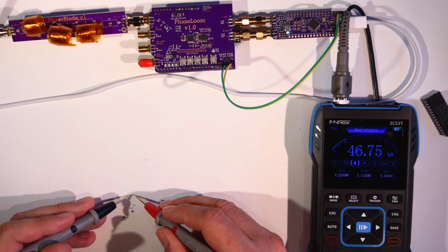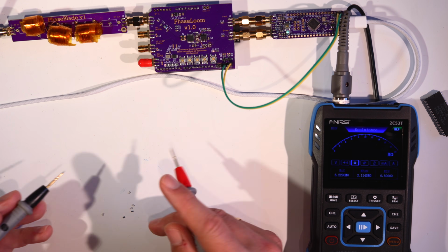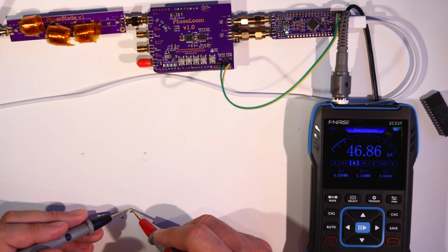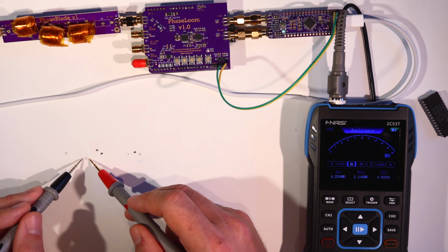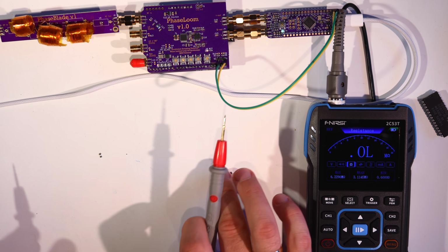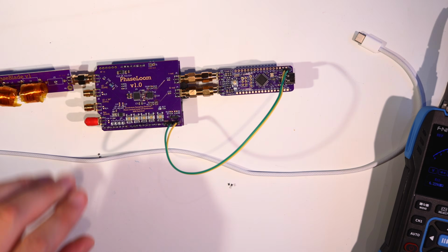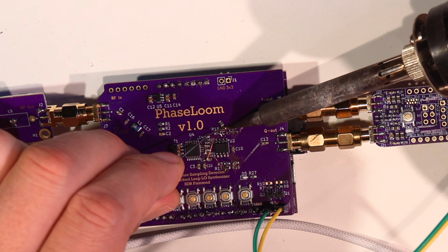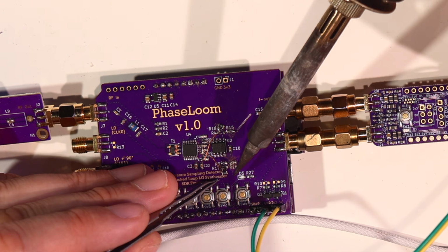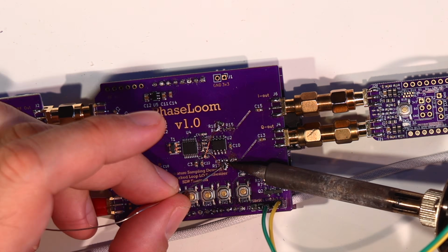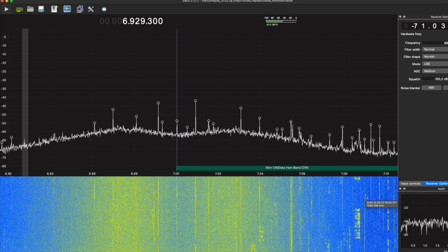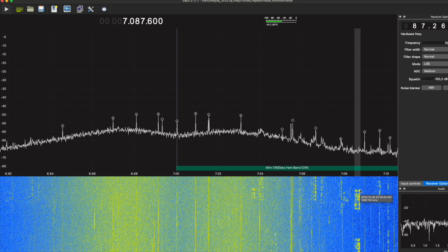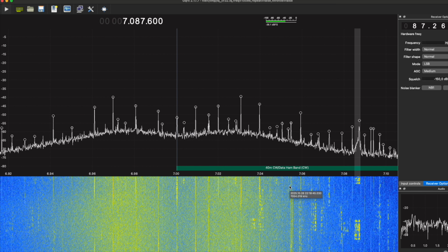I take a handful of resistors and I pick the two that are closest to each other in value. So even if they're sold as 1% resistors, we can find two that are within about 10 ohms of each other, making these resistors act like they're 0.02% resistors. With those in place, let's see if a stronger signal into the ADC makes things prettier. Back in the garage, things do look slightly improved, especially at the edges of the 200 kHz bandwidth.